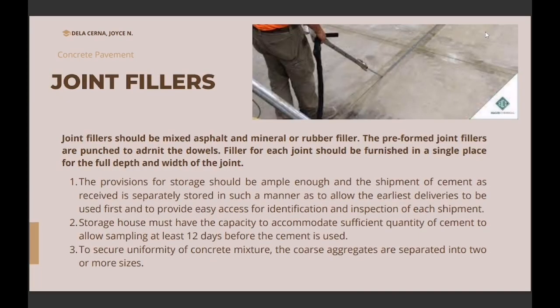Joint fillers. Joint fillers should be a mixed asphalt mixture or rubber filler. The preformed joint fillers are punched to adhere. The filler for each joint should be furnished in a single piece for the full depth and width of the joint.